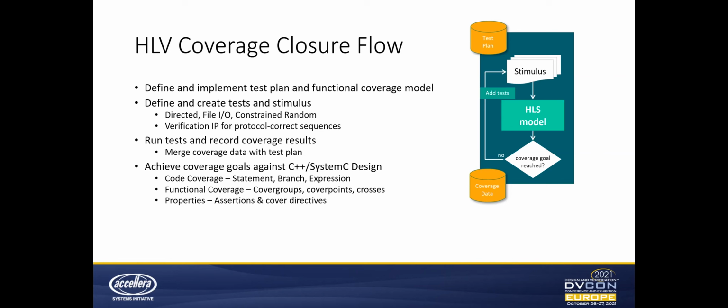Between the ability to leverage standard functional coverage metrics, the usual functional prediction checking, and the ability to collect and analyze code coverage from within that HLS design source itself, this allows us to achieve nearly all of our verification goals and resolve most of our design bugs before we push the design through synthesis to produce that RTL.